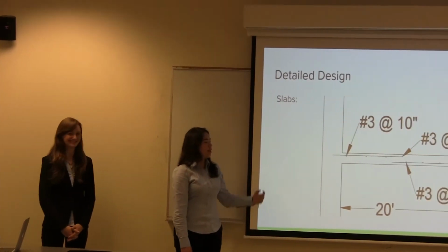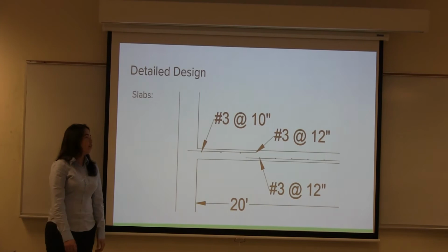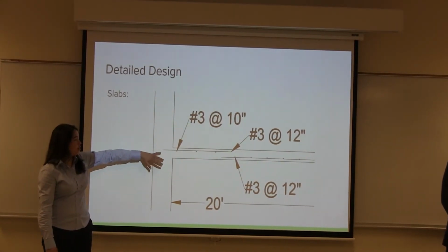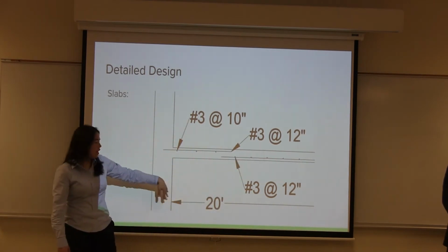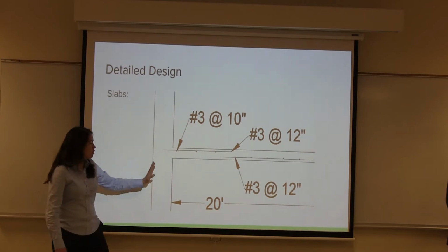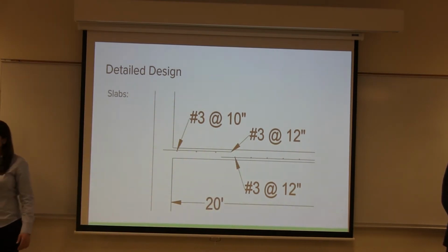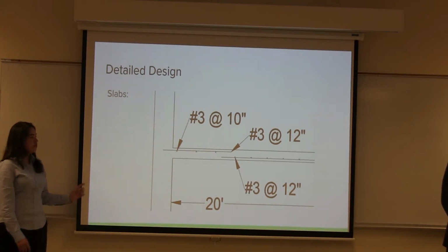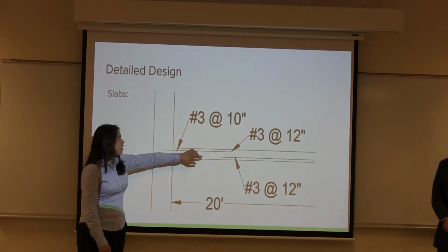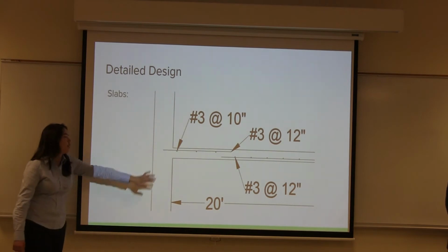And then also for the slab, we came up with the thickness and calculated the self-weight. We consider the slab to be fixed support here, and also here is only half of the span. So consider fixed at the end? No, this one is one input is this one. For the girders and beams, we consider two fixed supports. Yeah, because it's obvious, the reinforcement says this is not fixed. And then here is one example of our main reinforcement, and also the temperature shrinkage, and also for the bottom, and here's the moment.